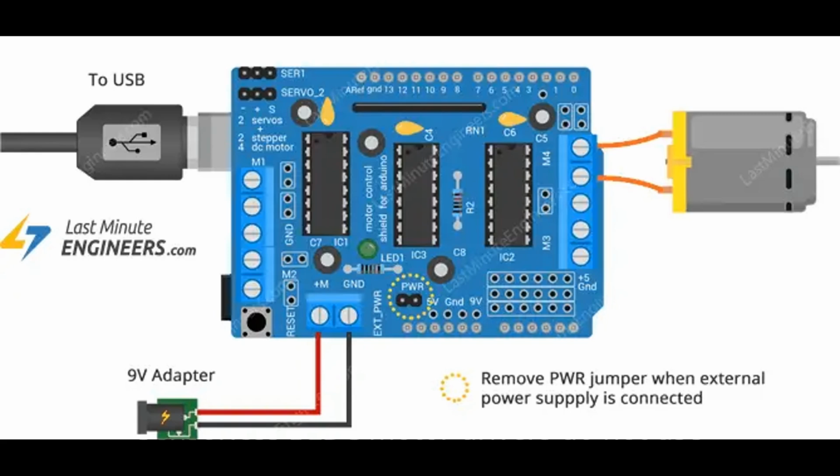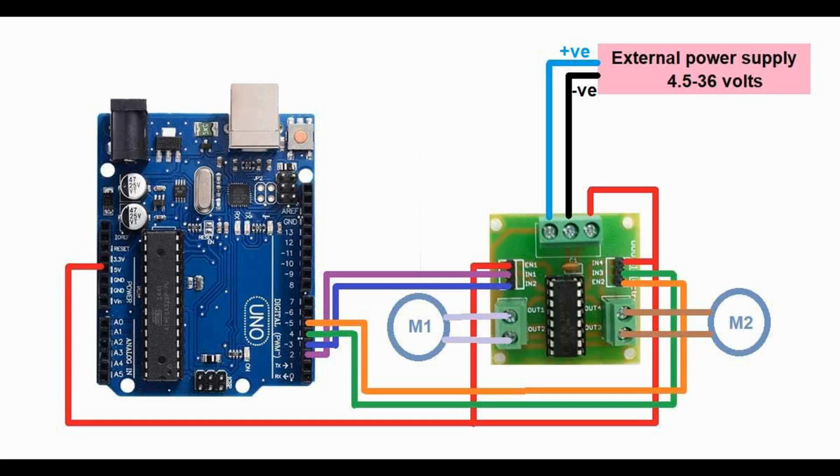3. Sensorless BLDC motor drivers. Function. Sensorless BLDC motor drivers do not use Hall sensors or encoders to detect rotor position. Instead, they rely on the back electromotive force, back EMF, generated by the motor to determine the rotor's position. Operation. Sensorless drivers estimate the rotor position based on the voltage generated by the spinning rotor, back EMF. These drivers are typically used when lower-cost solutions are required, as they do not need extra sensors. The rotor position is inferred indirectly from the motor's electrical properties.